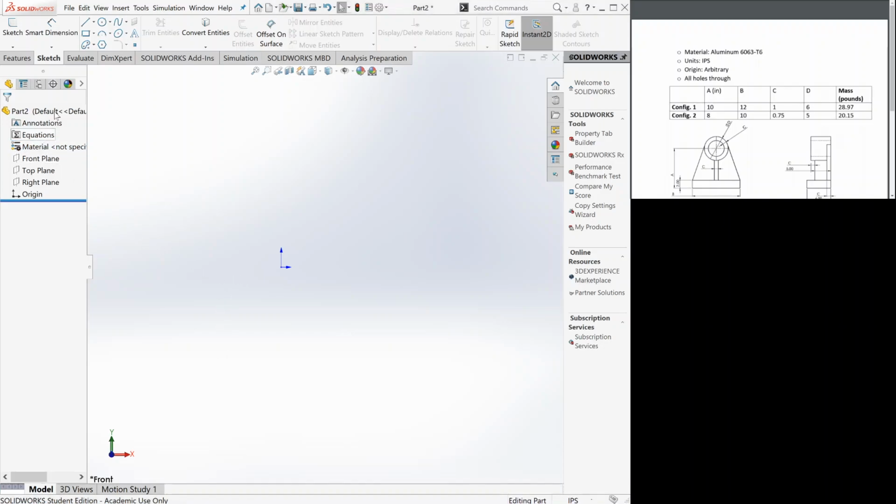Okay, so you're going to have equations right here in your feature manager tree, but in case you don't, you're going to go up to the little gear looking thing called options, click on it, and scroll down till you find feature manager. Again, scroll down and scroll to your right. It should be the first one on the top right lane, and make sure it's shown, not automatic, not hide, but shown. Okay, now again, right click, manage equations.